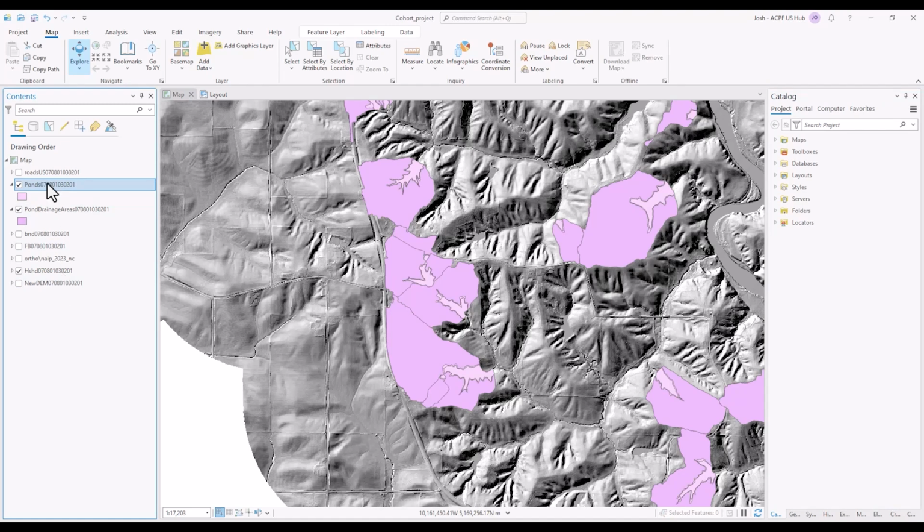It is possible that you have a low amount or even zero ponds. This is a tool that relies heavily on the local slope around the midpoint that is selected, so it's a very specific site that it's looking for. Before we change the symbolization on them, let's take a look at the attribute tables. Right-click on the ponds in the table of contents and click Attribute Table.